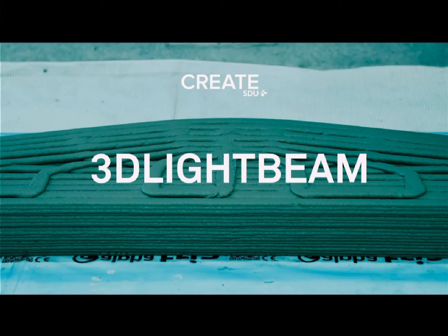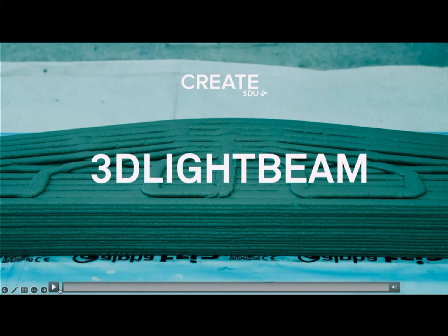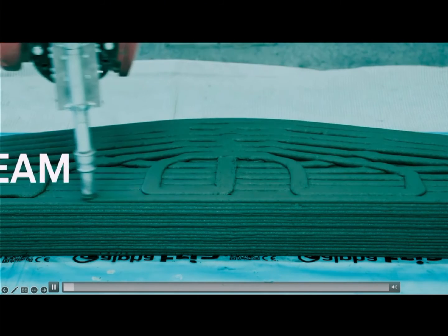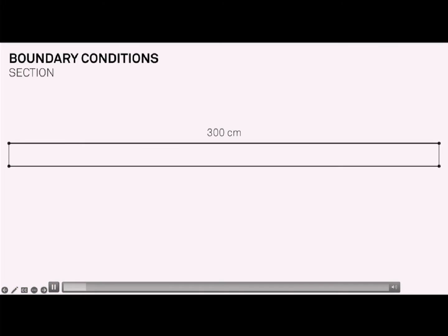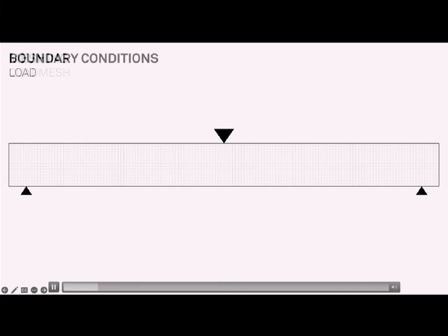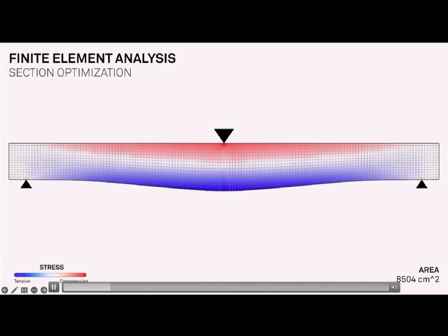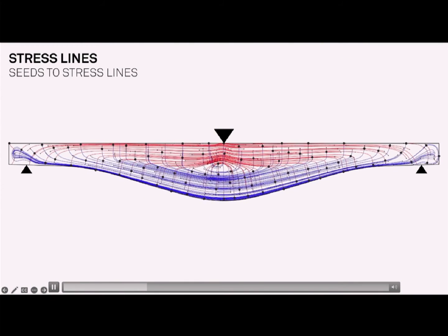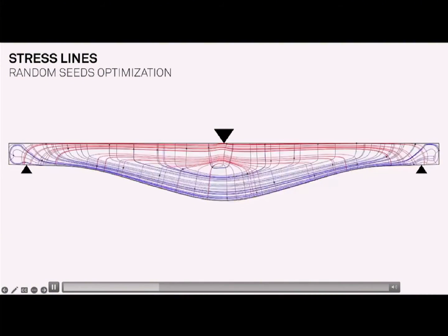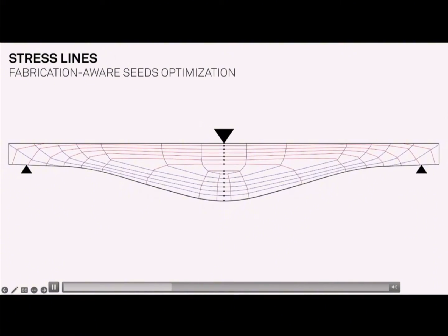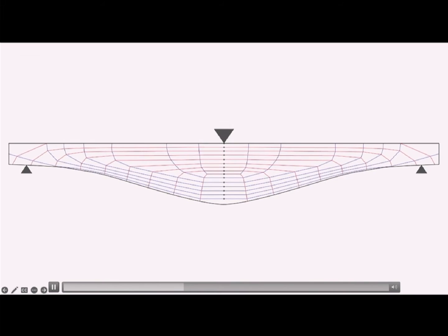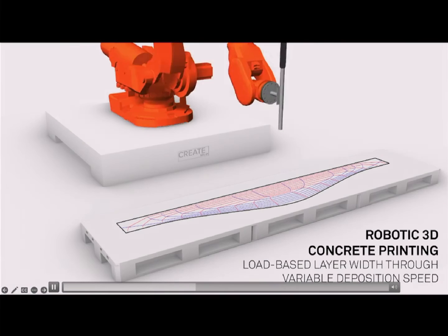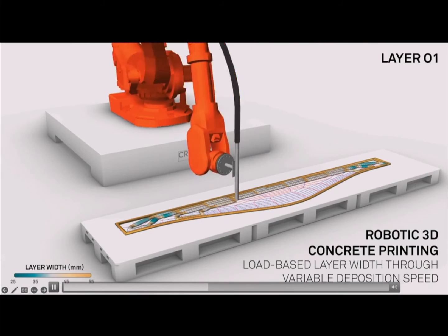And then the last step, I have a short video. In this case, on top of applying this porosity in the longitudinal section, given the case of a point load in the center, we also optimized the shape, so the external profile of our beam. And then the rest of the process is similar to the previous elements.